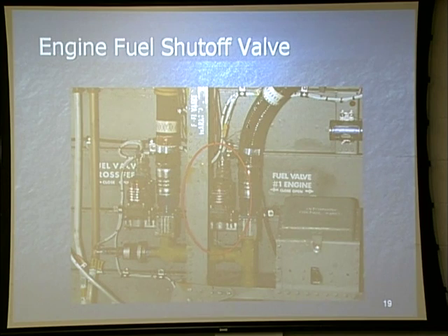Now, what I would do from time to time is I would just move one. I would just move the engine fuel shutoff valve. For the purpose of what? For the purpose I would want you to catch something's wrong. And then normally, you'll say, hey, these are both closed. We have a problem. So what am I trying to get out of you now? Well, which one's wrong? Depends where the fire handle stands.